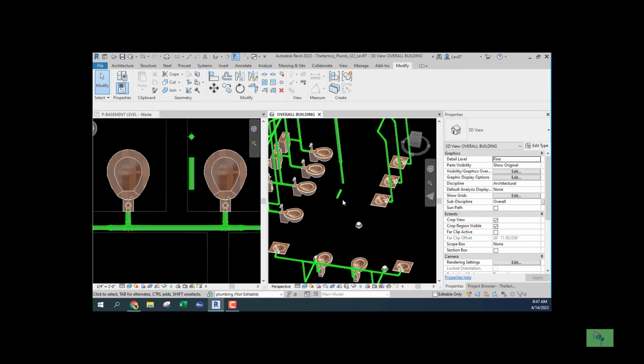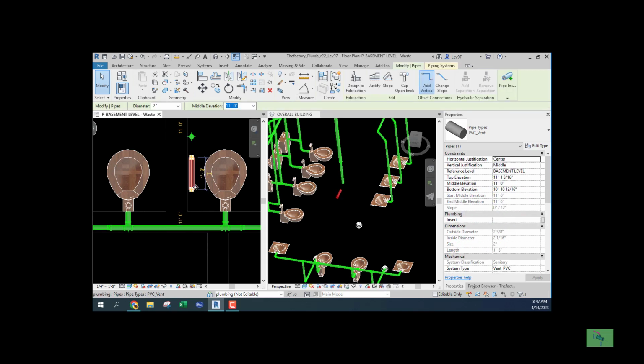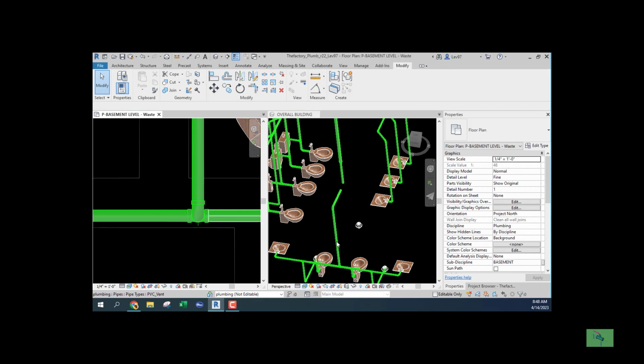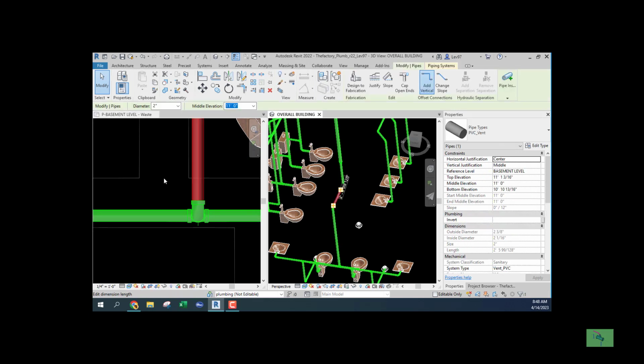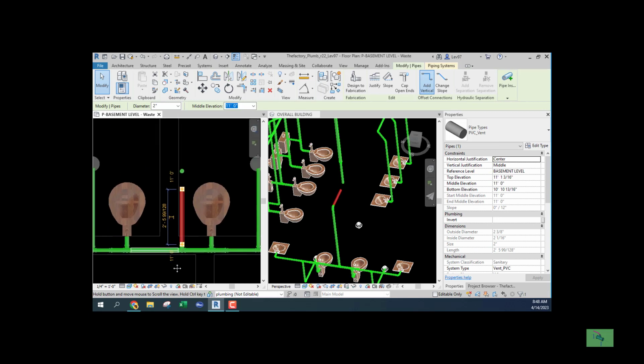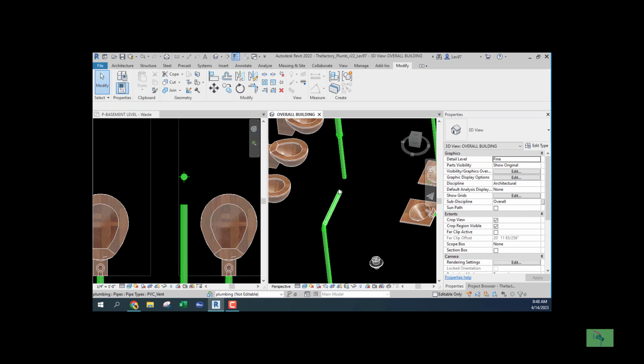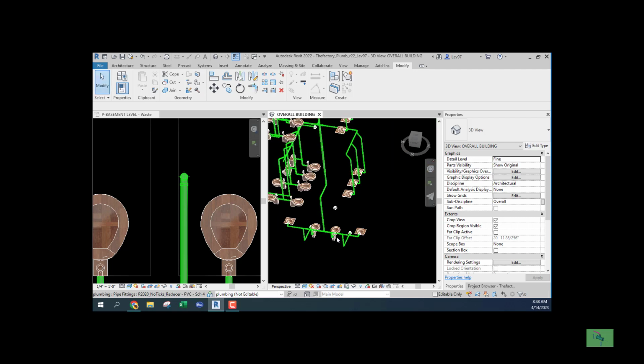So almost finished. I'm going to come here, and it's going to go down and connect into this pipe. So I'll draw this pipe, and we can go here and connect down. And once we're in this area, this is the area that we're in the ceiling space. And from here, we can just make a connection with a fillet. And everything looks good.